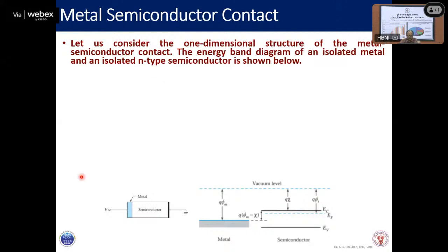So if you have a semiconductor and you have a joint with the metal, and you apply a potential here, why it will behave like a rectifier or Schottky diode can be explained on the basis of the band diagram. So you draw a band diagram where this metal which you have added here is placed here, and then the band diagram of this semiconductor you have drawn here.